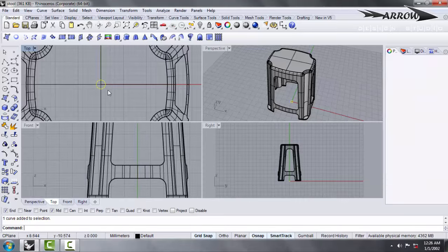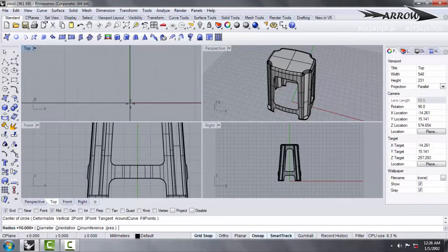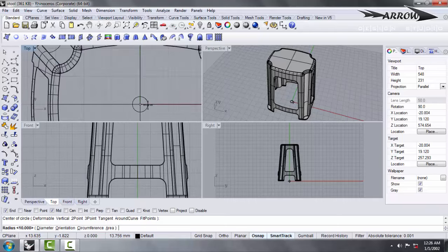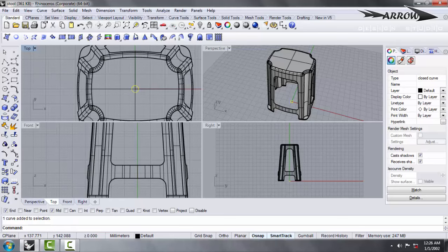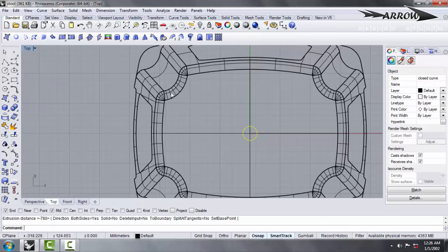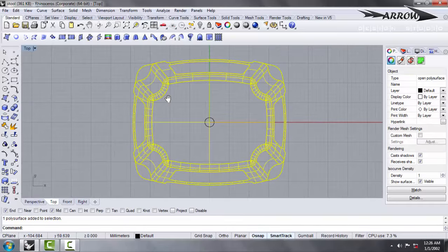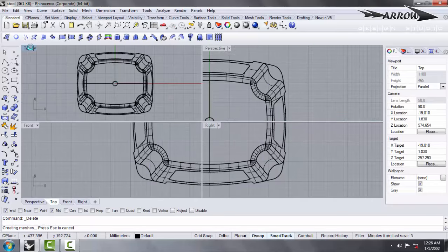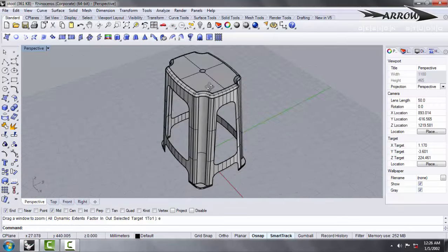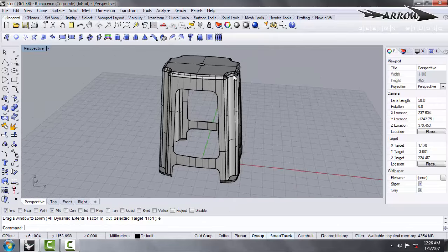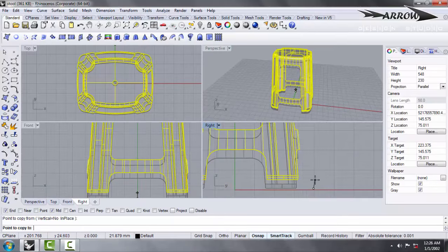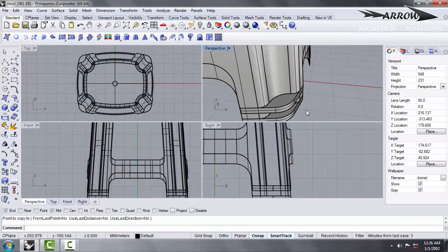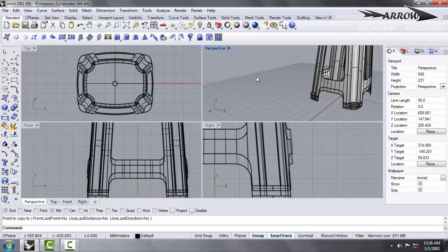now what I'll be doing is I'll be making a circle at the top for inserting a finger into the geometry and picking it up. I'll just make the grid snap off for a while so that I can get the exact, okay, this much is sufficient for us. I'll just say extrude, or not even, no need to extrude it. You can go in the planar view, anyone, top view, front view. In this case I'll go in top view, split, and then I can see this one, and I'll delete these two things. So I have my stool over here with a finger pocket to pick it up, and even if you copy it this way, you can see it can be stacked up.